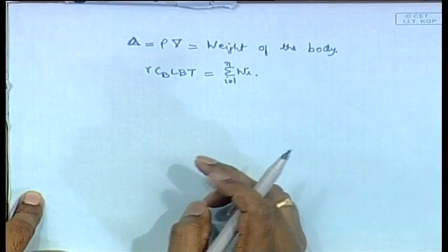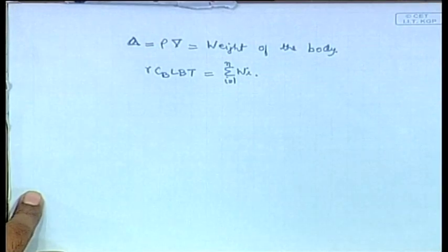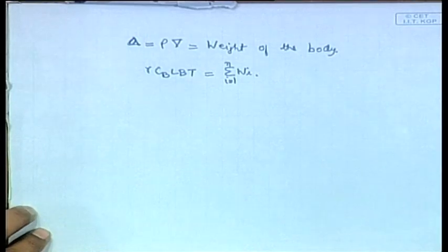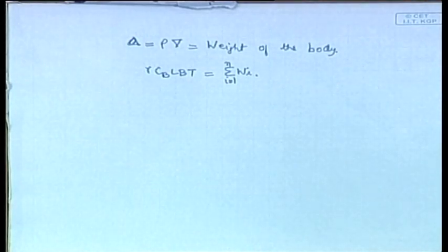Then the next important point that we talked about is how you tilt the water line instead of the body itself. You never tilt the body as such, you will never see such a drawing. Like we have shown drawings here, always the water line is tilted. The important point is that the water line is always horizontal. Another important point related to that, from G the weight acting is always vertical. So, that also you have to remember.